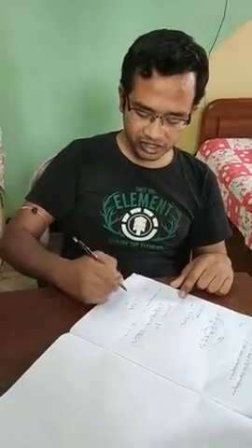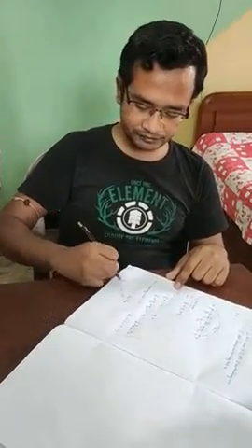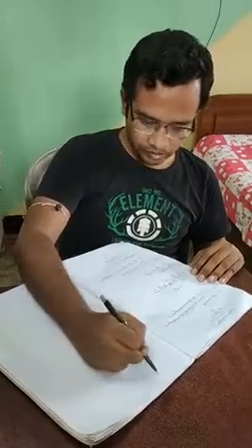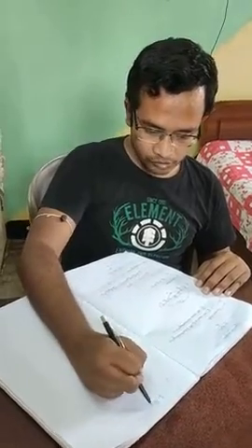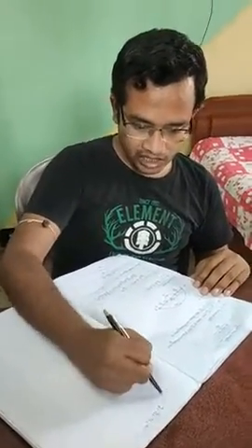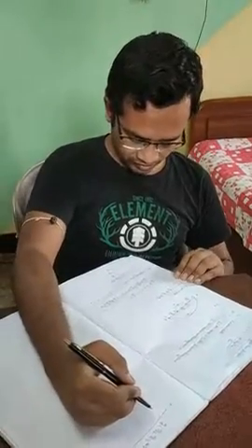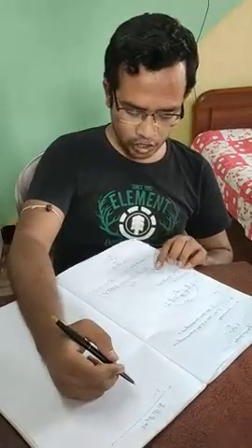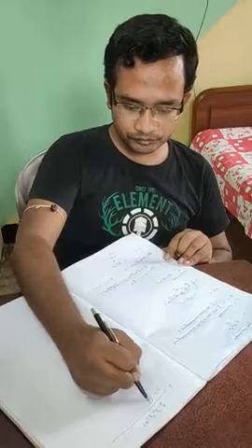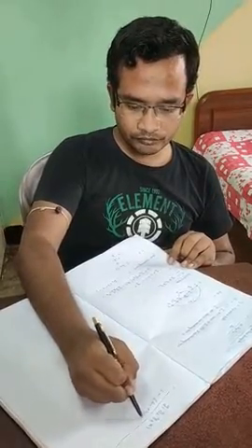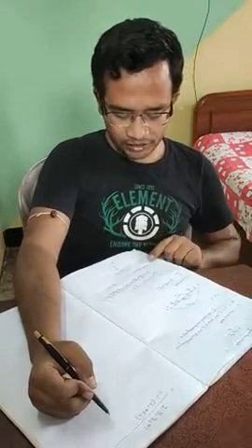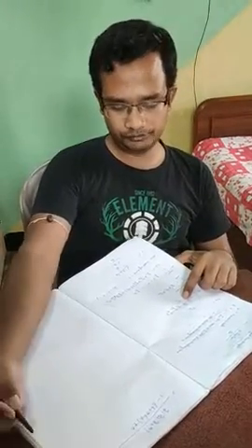So now summation Δk Pk means P1 Δ1 divided by Δ, which gives us G1 G2 G3 into 1, whole divided by Δ. Δ means 1 minus summation of all loops. That means 1 minus (L1 plus L2), plus summation of all two non-touching loops. Now see here, non-touching loops equal 0, that means in this graph there is no non-touching loop. So plus 0.